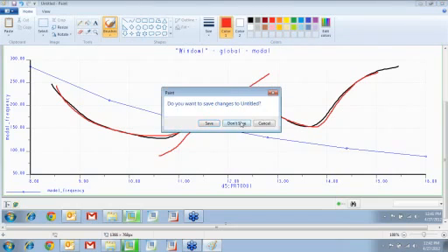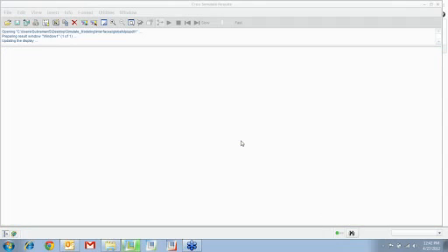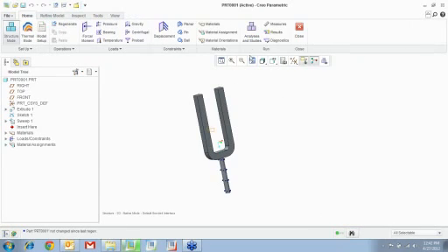So global sensitivity is very good. It lets you say, should I use this design variable in my optimization, or if I have to use it, what should be the range? You see the range needs to be 11.5 to 12.5, I'm sorry. So you go ahead and say, all right, let's run an optimization.